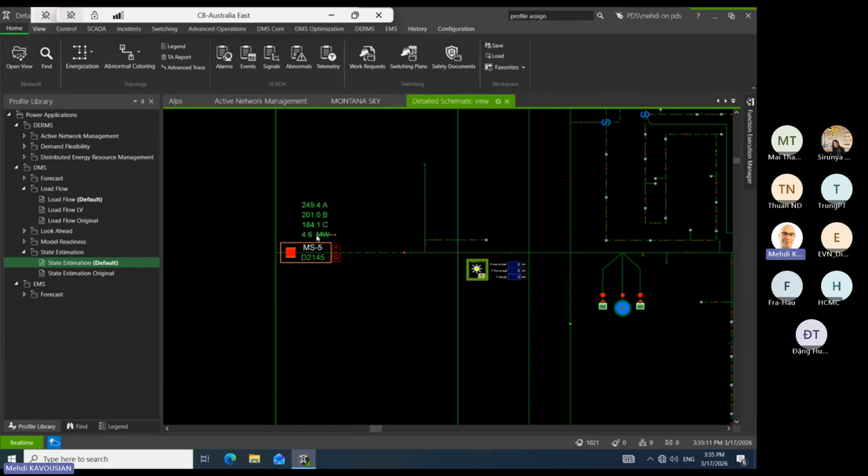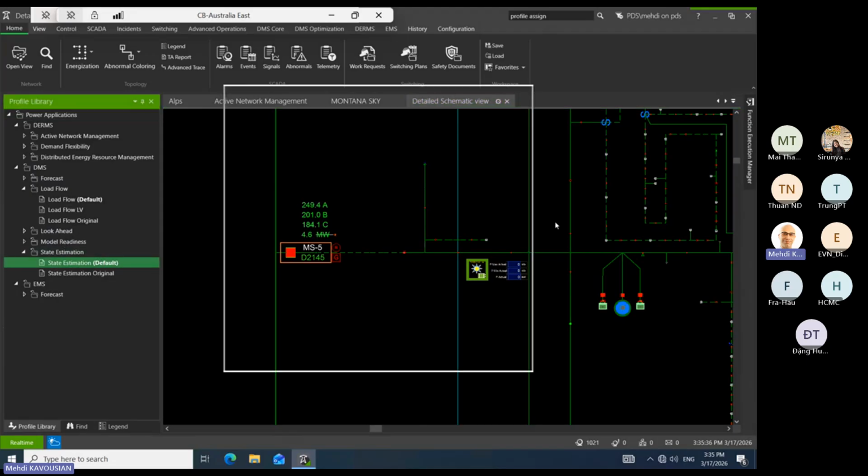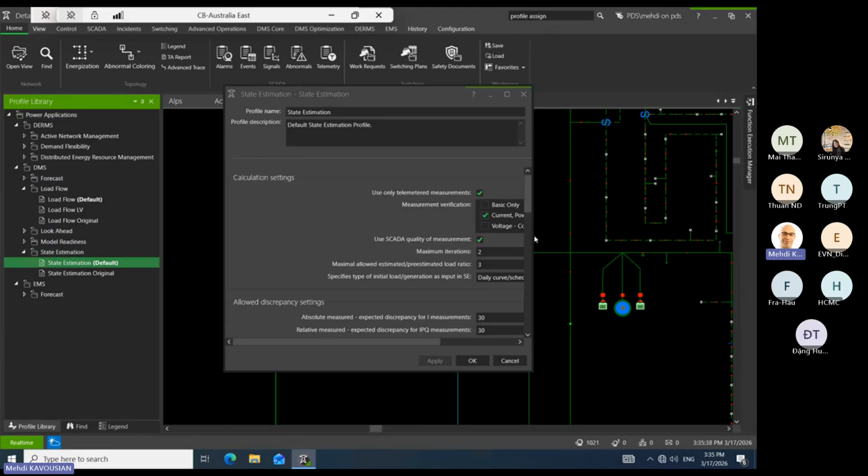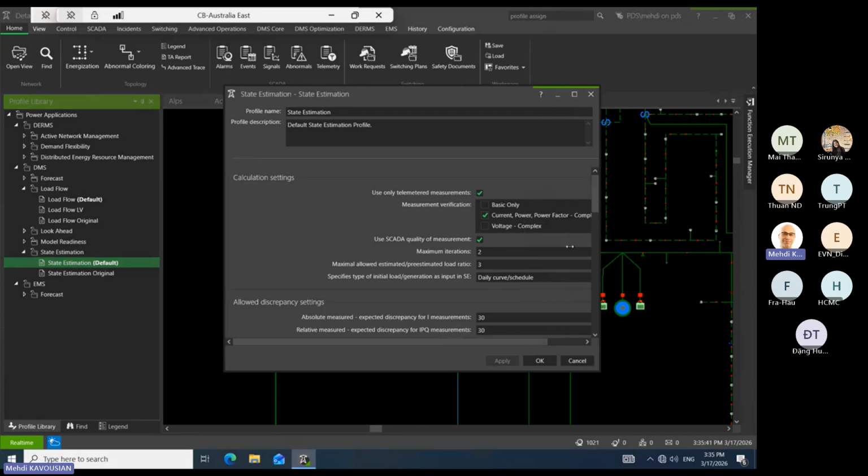Then for the measurement, if it's more than 3 times or less than 3 times that value, it will ignore it, because it says the load profile is this and the measurement is that, so probably the measurement is too far. But if it's within that limit, it tries to adjust them between each other. Sometimes we make 3 into 5 or 10. It depends. If we don't have a good load profile, we increase this.